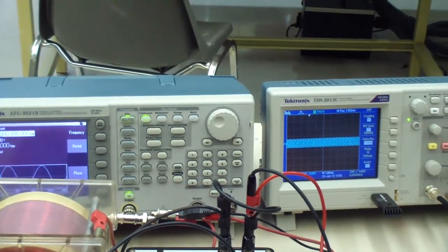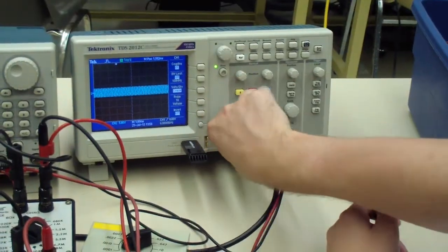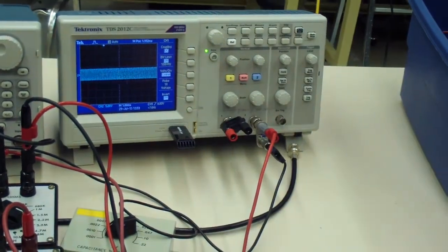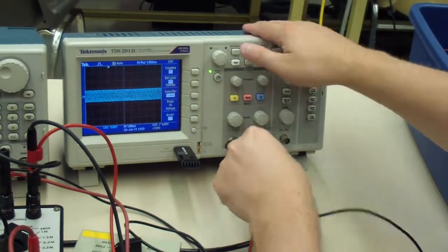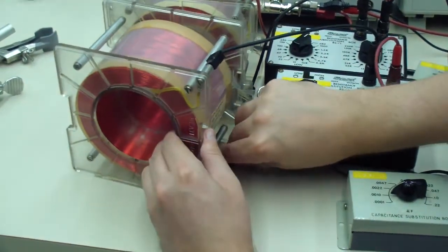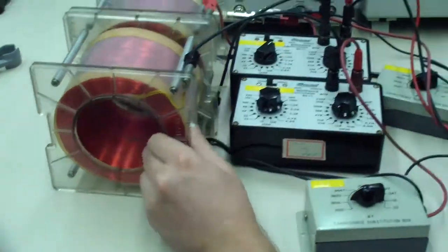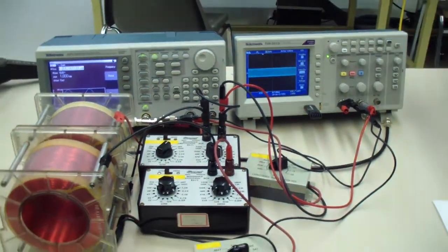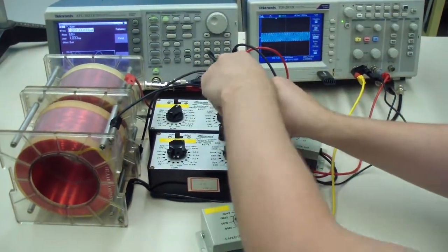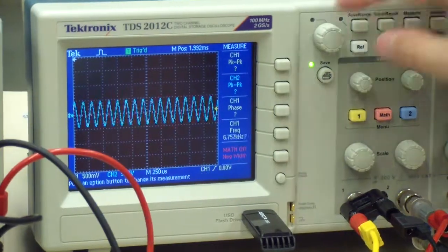If you choose to use the oscilloscope to measure amplitudes, remove the BNC cables from channel 1. Replace it with the BNC to banana adapter and connect banana cables across the coupled circuit's capacitor. Re-enable the channel 1 display. You can now measure amplitudes by pressing measure and using two of the available slots for channel 1 peak to peak and channel 2 peak to peak.